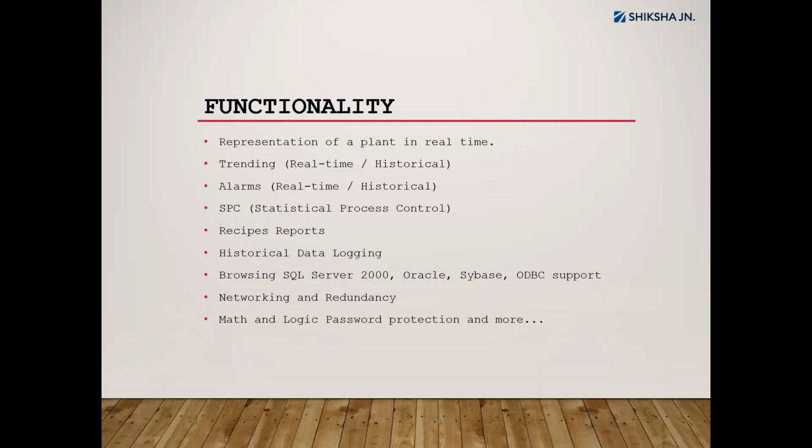Then when it comes to the features, like I was talking about, various functions can be embedded and integrated in the HMI systems. That can be done through the software. So what are these things? You can see trending is written there, real-time trends. That means some plotting system is there. Based on the temperature, what is the flow? Based on the time, what is the pressure developed in my boiler sections or turbine sections? That can be visualized through real-time trends. Trends are nothing but plotters. Between the X and Y axis, it will plot the graphs.